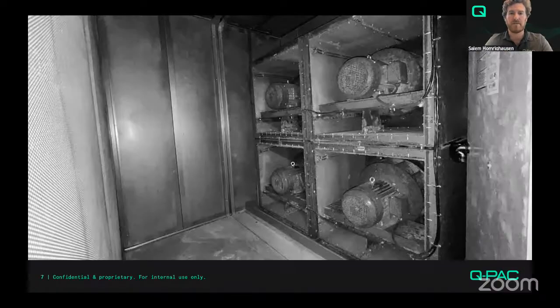Shortly after, I think it was in the 90s, when this product first came around, the direct drive plenum fan array became a solution for airflow for buildings. And a lot of times it's going to be applied in those critical spaces where it's unacceptable to lose a motor or lose a single blower for airflow for the space for any reason, right? So these are places like hospitals, data centers, manufacturing facilities, anywhere where no airflow means your operation is not operating,